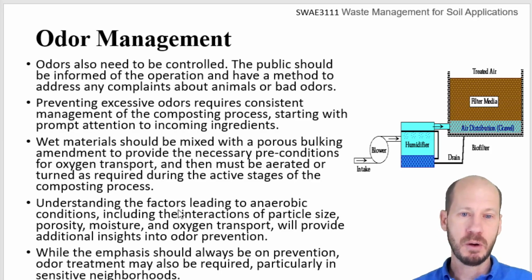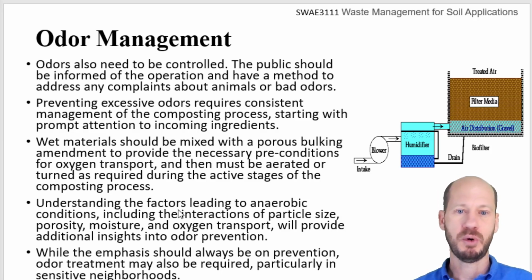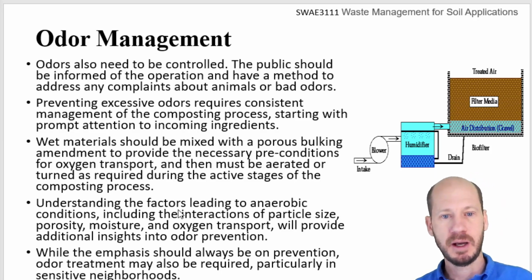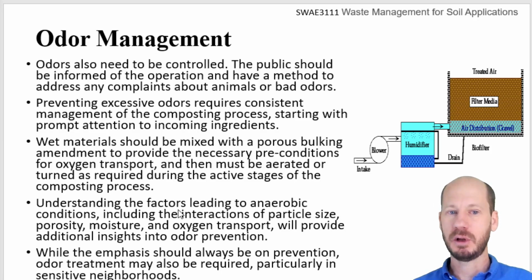So the feedstock calculation is one important step. The type of aeration system that you have, the temperature cycles that you are observing during this composting process, all these must be managed in order to reduce the odors. Yeah, the porosity of the material, if the porosity is low, you might have anaerobic conditions and you might need to manage odor. If all these things do not solve your odor management, then you have to implement some system for removing the odor. Yeah, the odor treatment system.